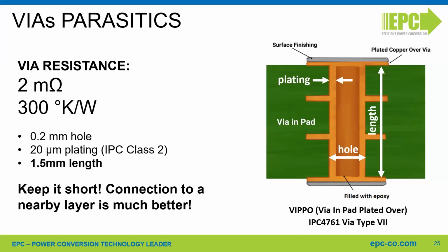Okay. Is it also a good practice to place a footprint for an additional gate capacitor for tuning purposes, like with MOSFETs, or is it something to avoid absolutely? This is specifically for a motor drive application. Yeah, you can place a 0402 size capacitor between gate and source that can be used for debugging purposes. For tuning the turn on and turn off speed, we do not recommend to add capacitance to the gate, but just to increase the gate resistance.